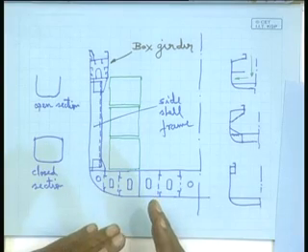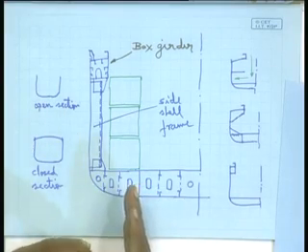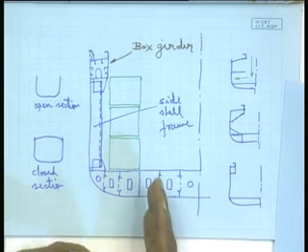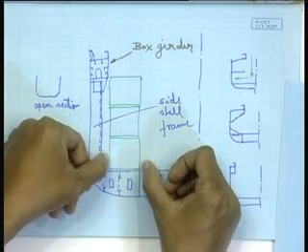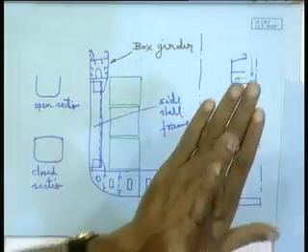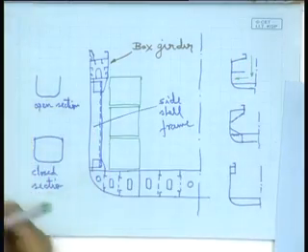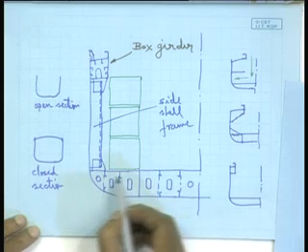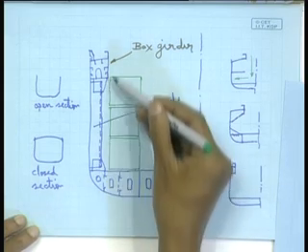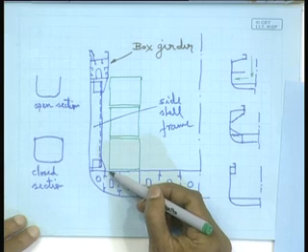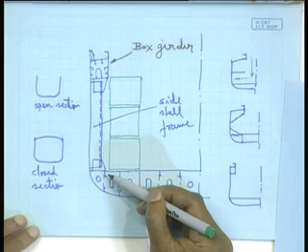So, the side shell is transversely stiffened, and the double bottom you can see is the same as in any other vessel. The only thing to be seen here is that the frame spacing etc. should be taken in such a fashion that these containers sit truly on some longitudinal. In this drawing it is not very carefully drawn. As you can see, this edge of the stack of containers is not sitting on a longitudinal. This is not correct.